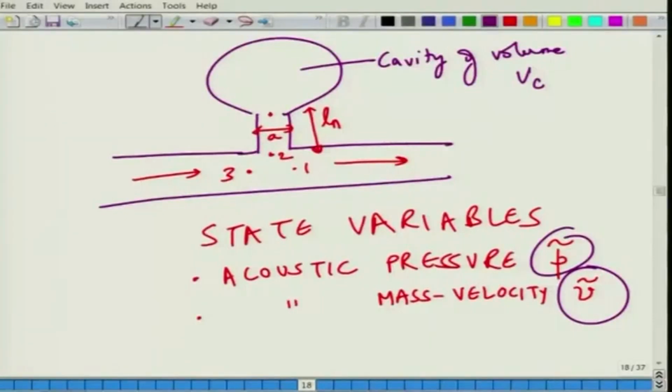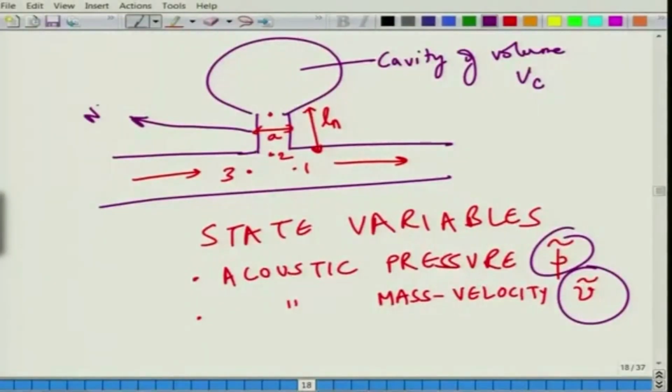and why do we use such a peculiar looking structure? This Helmholtz resonator has actually been quite popularly used for several decades, typically for controlling certain tones or controlling noise in a very narrow band. Typically in air cabins of aircraft and some other machinery where tonal noise is dominant, we use not just one but a series of Helmholtz resonators, whose length, this is by the way the neck or the throat, and this is the cavity, and this is the main branch or the main duct.